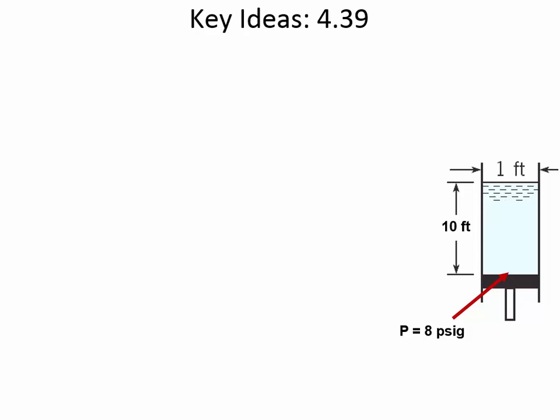So there's 12 inches in a foot, and it's a square foot, that means that 1 pound in a square inch is the same as 144 pounds in the square foot. So keep that in mind, that 1 psi equals 144 psf, pounds per square foot. Because you'll be working this problem with distance of 10 feet, and so you'll need to convert the pressure into pounds per square feet.